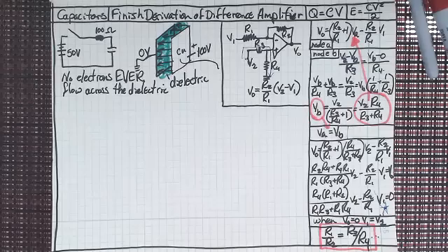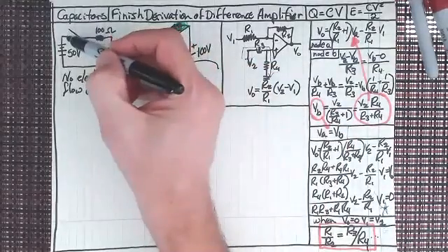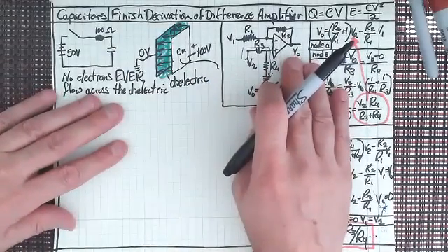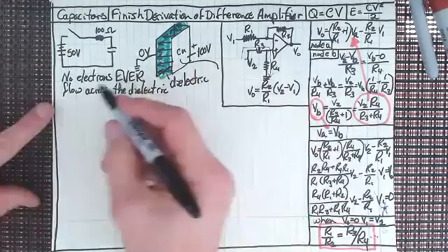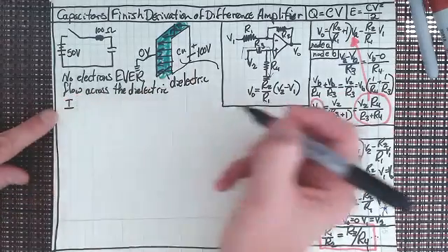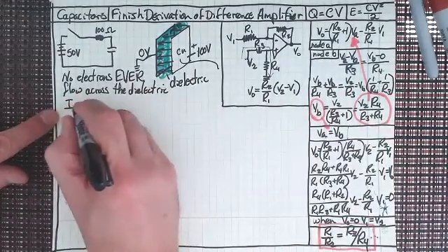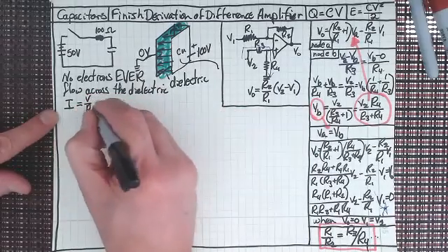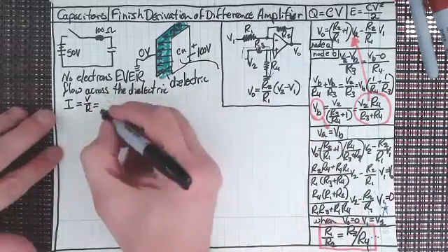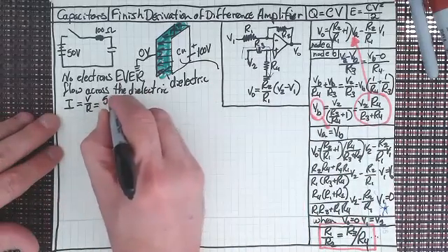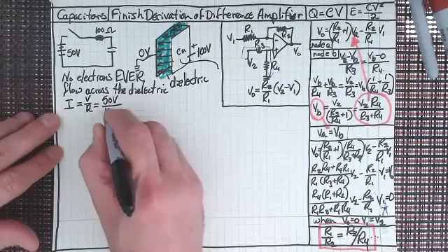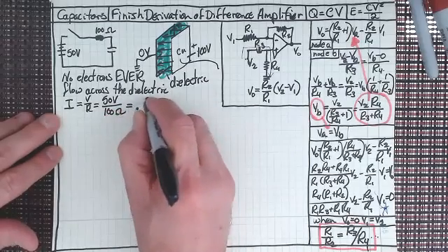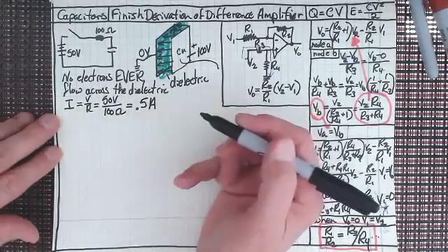So you're probably saying, well, when he throws that switch, what's the current going to look like? What is our maximum current? Our maximum current, I don't even have to write Ohm's law anymore, is going to be V over R. So our maximum current is going to be 50 volts divided by 100 ohms. That's 0.5 amps, isn't it?